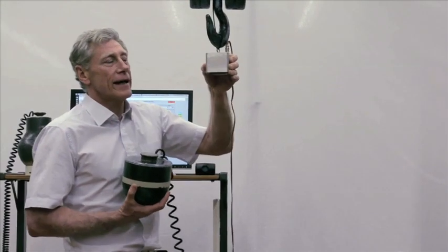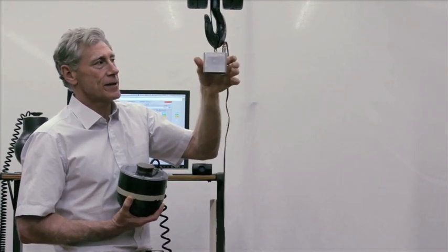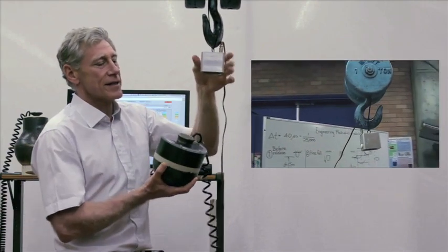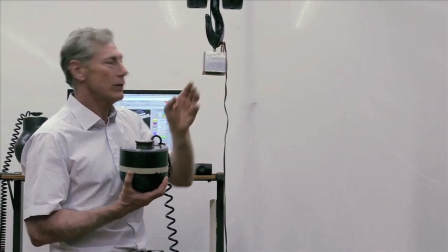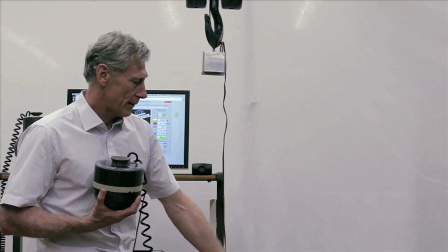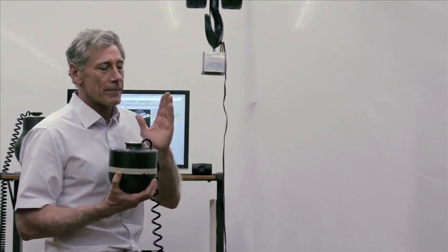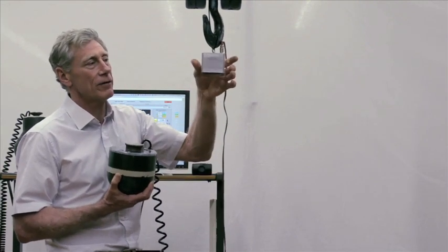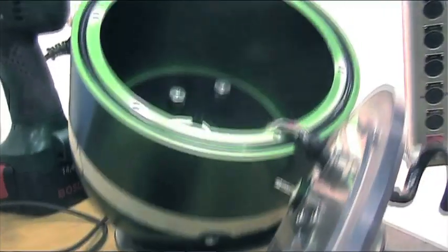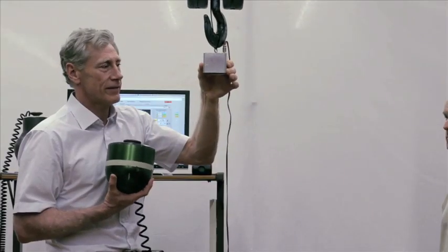It's important that we get a clean release, and we've designed an electromagnet. It's a permanent magnet that releases the head form very cleanly, and we drive the field away with batteries. So when you hear that buzz, it's releasing the head form. It has a safety factor of 3. The head form, we assume, is 5 kgs, in this case it's 4.6, and the magnet can hold 15 kgs.